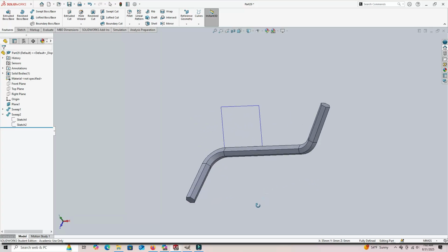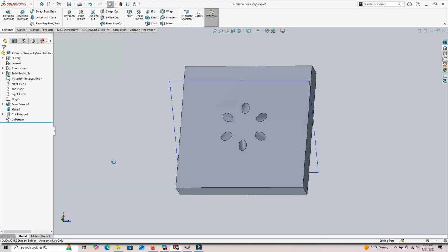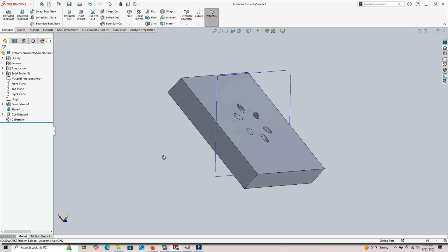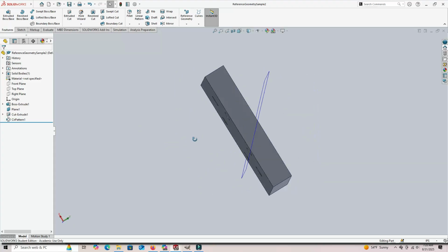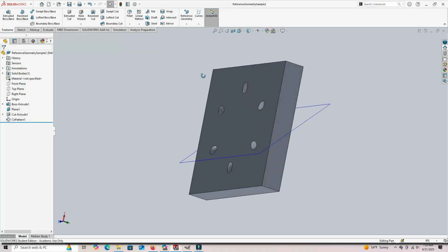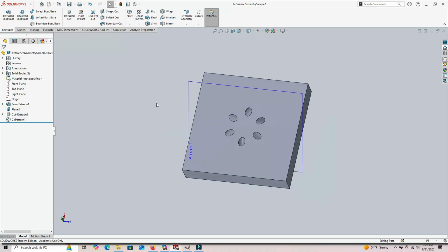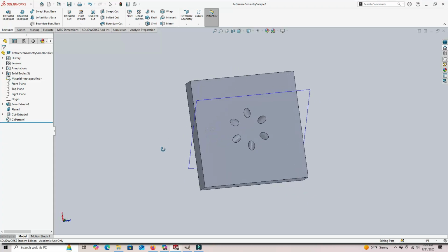This certainly isn't the only reason you would ever use reference geometry though. So let me show you another one. For this part, I'm bringing back all the hits. I've got an extrusion, I've got reference geometry. From that plane that I created, I have an extrude cut right through there, and then just for giggles I threw in a circular pattern, so we actually have that same extruded cut sent all through this part. And this would be a really interesting one to machine,